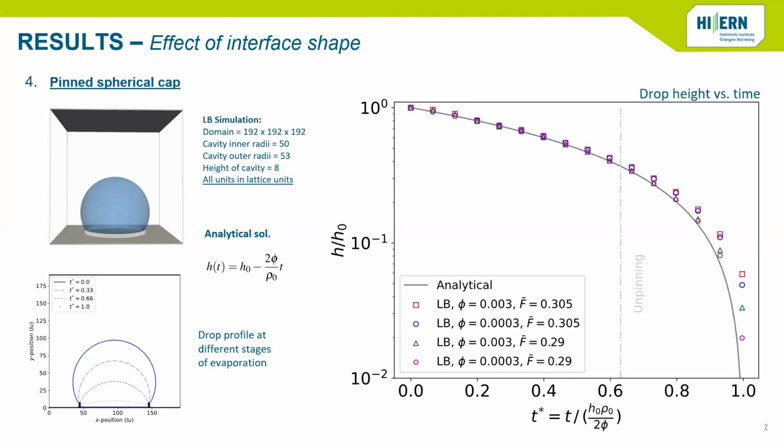For diffusion-limited evaporation, it's the opposite actually. There, it's r squared that varies with t. So there is a difference in evaporation rate. The scaling difference is there. That's why I stress the fact that there's a difference between diffusion-limited and reaction-limited evaporation.